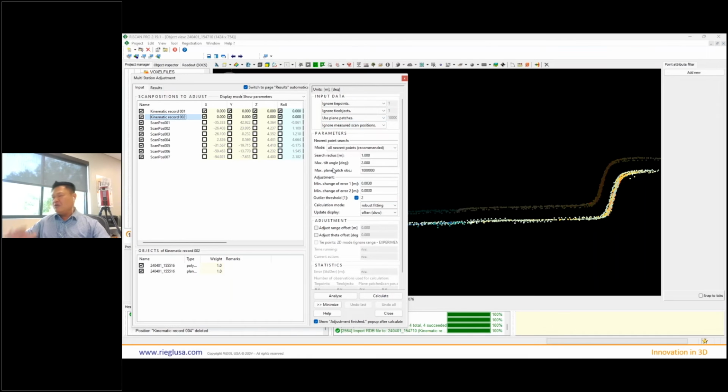So people will tend to get the GPS versus control kind of mixed up. When your data is registered down to survey control, your GPS information is suppressed, right? So regardless if you had good GPS or bad GPS, if you're using control, your data is suppressed. The only time that GPS is very important for an application is alpha survey, in my opinion.